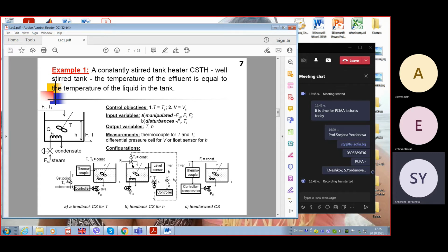In the other variant, we have a different control action. It should react to the magnitude and the sign of this error in a different way. To increase measured level, we have to decrease the opening that lets liquid out.